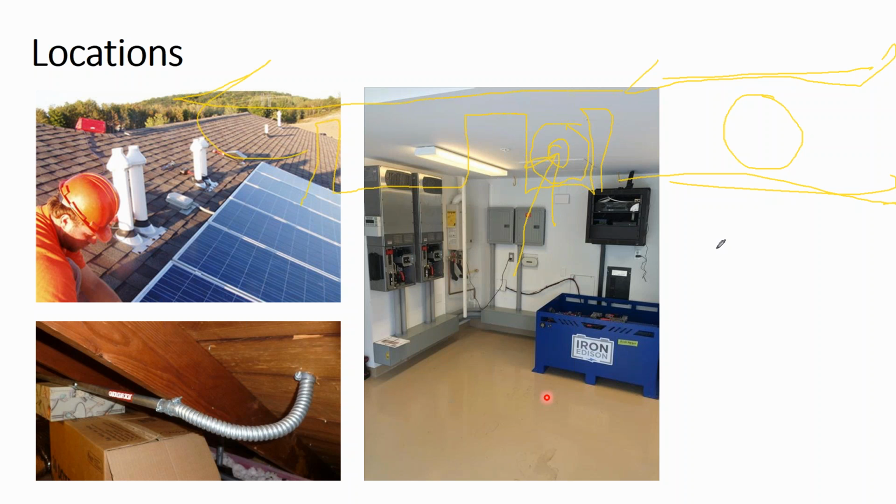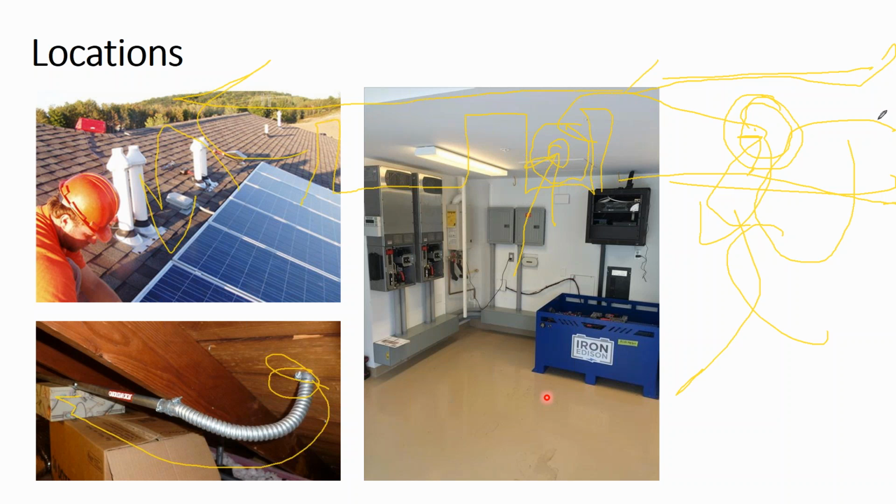You might say, well, is that code compliant? Can we just drill through the roof cap and go into our building? As far as the National Electric Code goes, yes, it is compliant, but what you have to comply with is going from this hot, wet environment into this conditioned, colder environment. So you put your fitting in, and that fitting has a hole, and you take solar cables and cram them into this hole. One solar cable coming in, and another, and another. And there are still gaps of air in that hole.